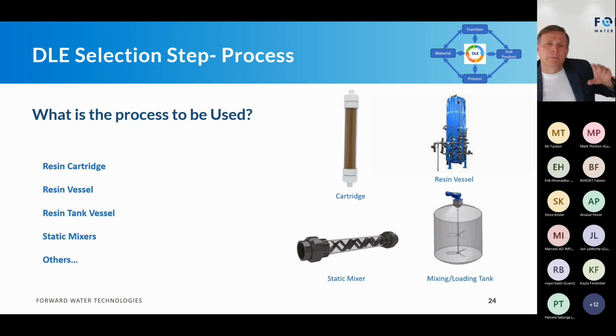And in doing so, if I have a cartridge, as you can guess, then I have to force the brine through the resin. I could have short circuiting or channeling within the material. Let's say the materials aren't packed evenly, and I've got channels that run through the side, so I can have short circuiting of the brine going through the resin material. So how that resin is packed and configured in the vessels is critical, because I can get bypassing and reduced performance from that.